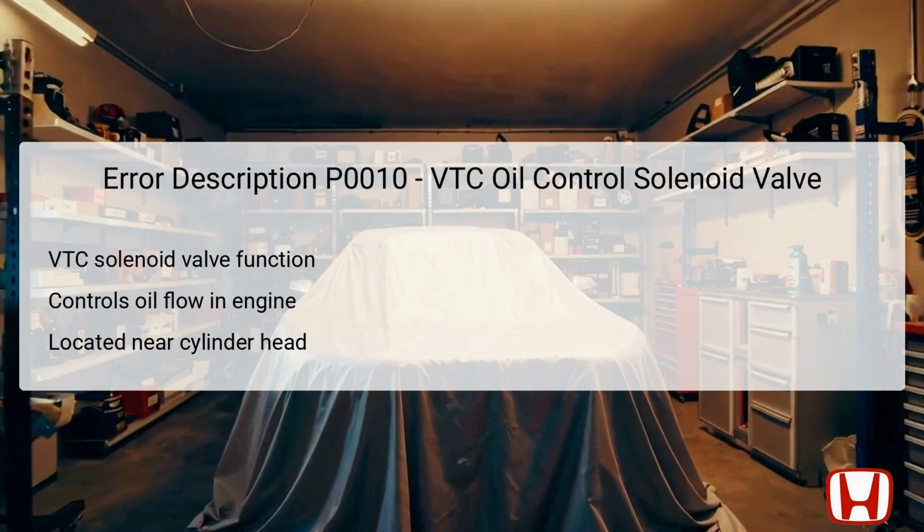The VTC oil control solenoid valve serves a key function in managing oil flow, crucial for the variable valve timing system. This component directly affects how the engine's intake and exhaust valves are operated, thereby enhancing performance and fuel efficiency. Positioned near the engine's cylinder head, it allows for precise control over the timing of valve operations by adjusting the oil pressure in response to the vehicle's operational demands.